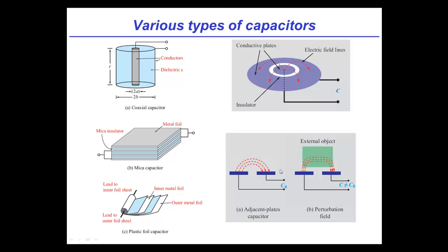And of course, as Michel pointed out, you can calculate this capacitance between two plates that are side by side. While in theory there's of course a capacitance that extends between any two objects, in reality we deal with this only for objects that are relatively close to each other. Yeah, that's right. And what's a really cool side point here is that many types of older touch screens that were capacitive relied on this idea, because if your finger comes down and rests somewhere between these two, it'll change the capacitance. And so if you're constantly monitoring that, you can detect when a finger is near. That's right. Not exactly how it's done in modern smartphones, but it's a predecessor idea to the modern way to do it.